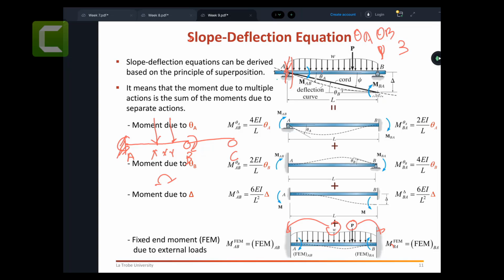So first, we clamp it, we arrest all the joints to make them fixed, to make it a kinematically determinate structure, to make the kinematic indeterminacy equal to 0. That is our first job. Does everyone understand that? We go there somehow, bang, we put the nail, we put the hammers, and then we say that this joint doesn't rotate, doesn't displace. We fix it. We use plates and we weld it, or we do the clamping and all, we fix it. Okay, that is job number 1. We just fix it, make the kinematic indeterminacy 0.